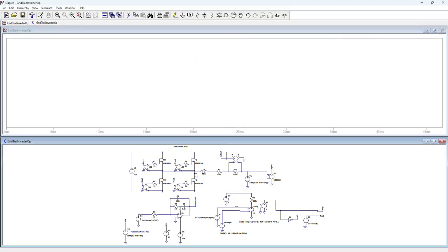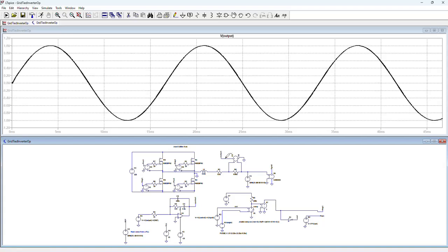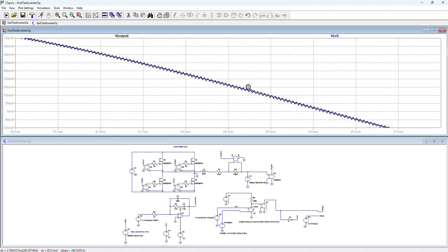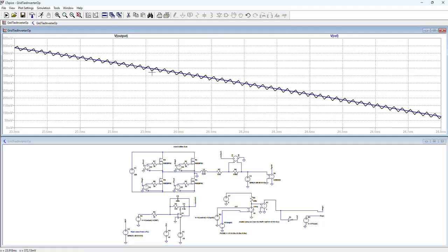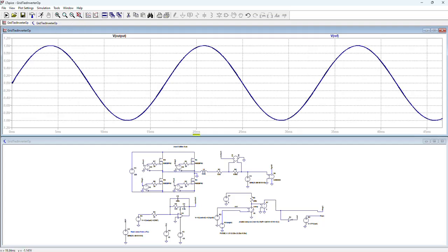I will include here the output signal of the sensor, which is a sinusoidal waveform representing the output current but varying from -1 to 1, and I can check it together with the reference to see if they are coincident. If I apply a zoom anywhere, I can see that my output current is following the reference as expected. So this is the first test to verify if the controller is good.